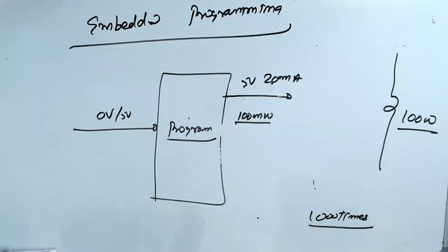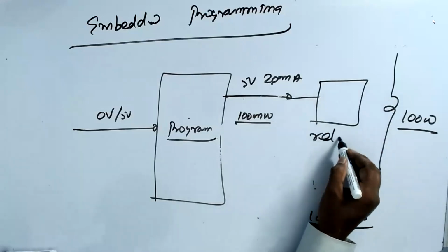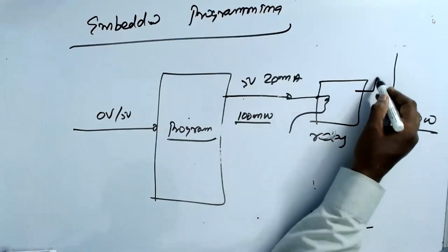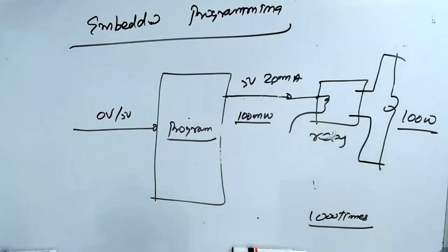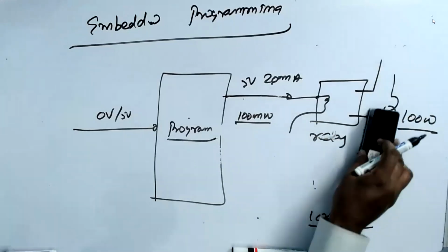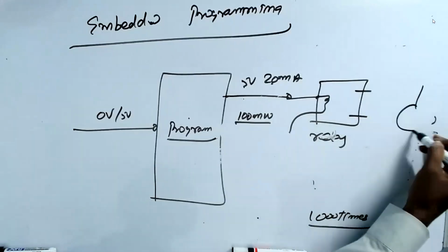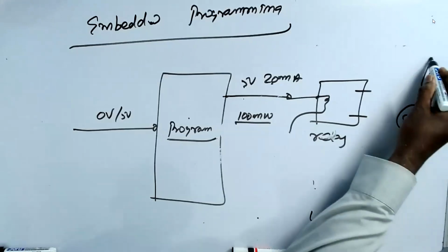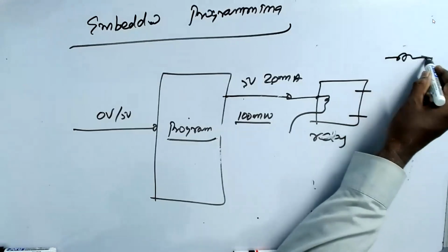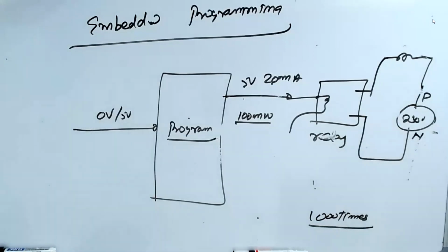The easiest device people use is the relay. You have an input to the coil and control, and here there will be two inputs. But they don't give any voltage; you need to connect it. You need to connect them like this. Take a supply, connect the bulb, connect to neutral, phase and neutral. Now you see that connection?